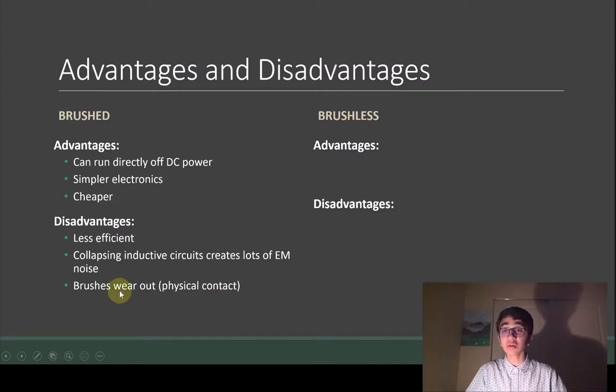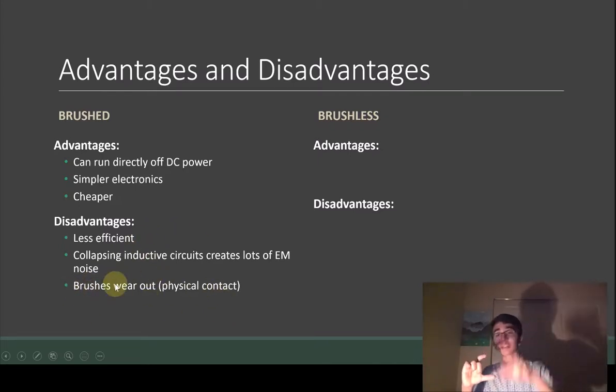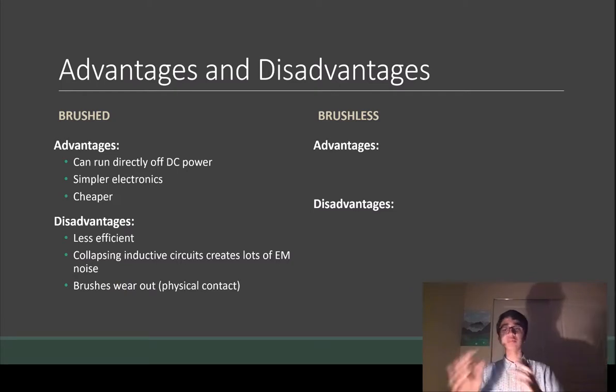Another disadvantage is that the brushes wear out over time. Remember, our brushes are making physical contact with the commutator, and just like anything that's constantly rubbing, it's going to wear out over time. This makes brush motors slightly less reliable and slightly more maintenance.